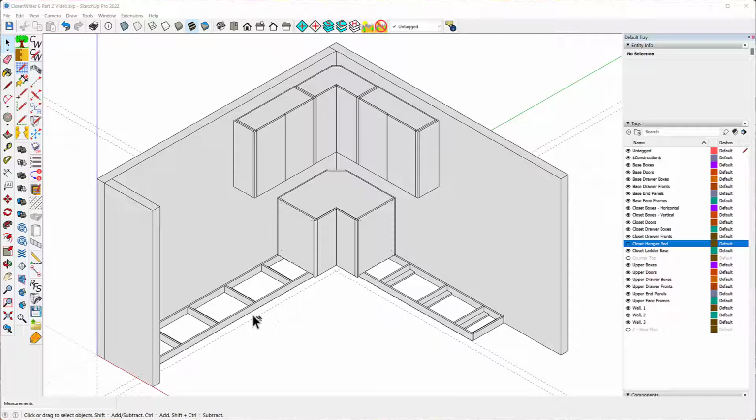So we use the insert a door and insert a drawer tool to place doors and drawers on top of that. So if I make this 24 inches from the wall and draw my closet and then add doors and drawers, the actual face of the doors and drawers will be something like 24 and 13/16 instead of 24 as they are in cabinets. You have to take that into account.